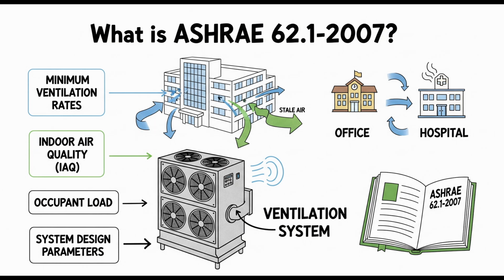Ev accounts for this whole system, in fact, how efficiently the outdoor air gets distributed to the zone that needs it most. It tells you how much total outdoor air you need at the main intake to satisfy the requirements of all the zones. Appendix A has the detailed calculations. Okay, so even the recipe book, the VRP, involves checking how air moves in the room and how it moves through the whole system to make sure people actually get the fresh air calculated from Rp and Ra. Exactly. It's prescriptive, but not that simple.